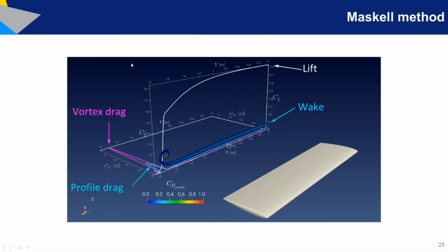Now let's bring this to a more practical region. Let's consider the case of CFD data for a rectangular wing. Let's say that I can get the wake data at a given survey plane position, and at that plane I have everything. I have the total pressure deficit, I have the actual kinetic deficit across the wake, I have the actual vorticity, so I have everything to compute the far field method based on the Maskell approach.